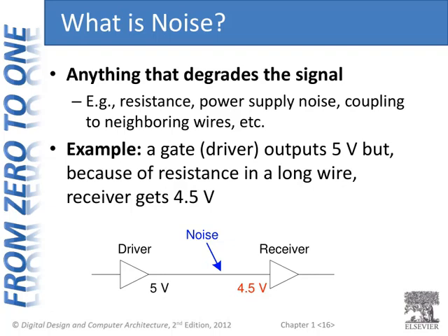That voltage supply can also vary. Maybe a neighboring wire is pulling up and could pull that signal up as well, causing noise on the signal of interest. So there are bunches of reasons for noise. I'm not going to test you on these reasons in this class, but it's important to know that they exist.